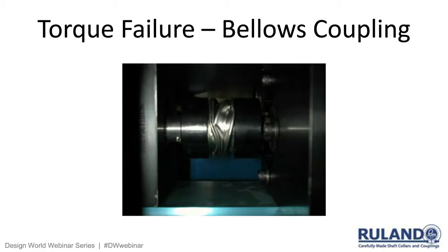Just a note, because of the design of bellows couplings, that bellows in the middle is thin stainless steel tubing, and when it does start to fail, a lot of times a crack will develop in the bellows, and you can hear it in operation. It'll make a snap, crackle, pop kind of noise as that crack in the bellows opens and closes. So if you've got an application for a bellows coupling and someone says it's making cracking noises, it's making popping noises, it's near the end of its service life, and it's time to order a new one because it probably won't last much longer in service.